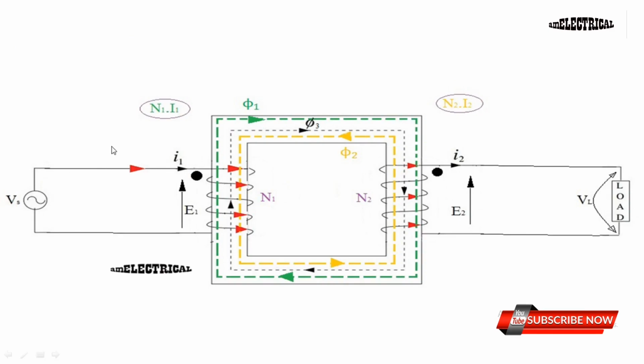Now the increased amount of current, that is the extra current, will again generate extra flux, which is here phi3. This phi3 will nullify phi2. This way, as long as the secondary side produces some cancelling flux, the primary side will also produce some flux which will nullify the cancelling flux.